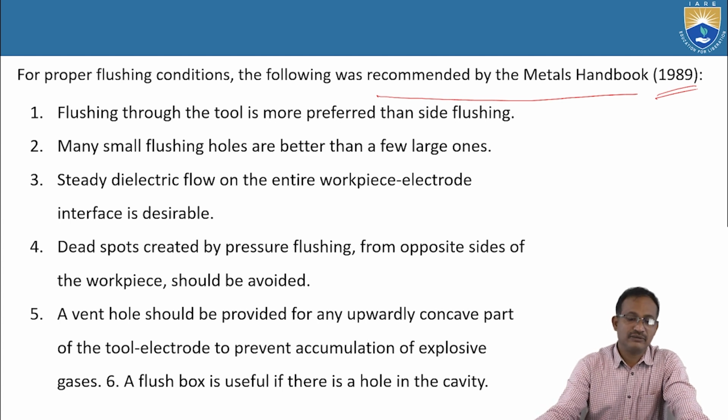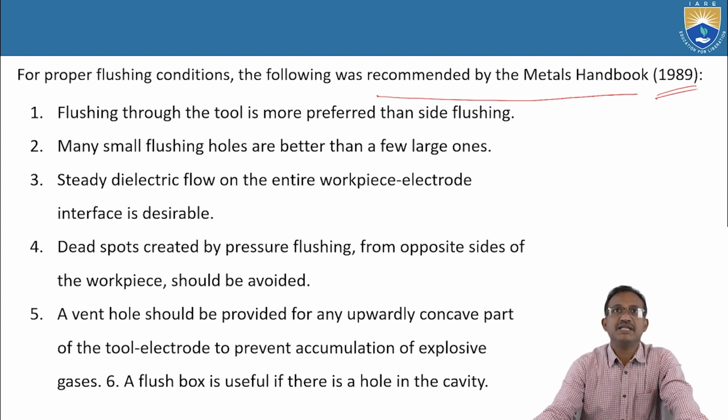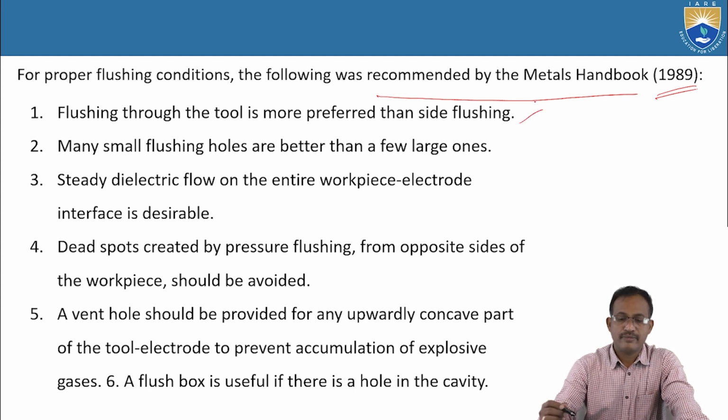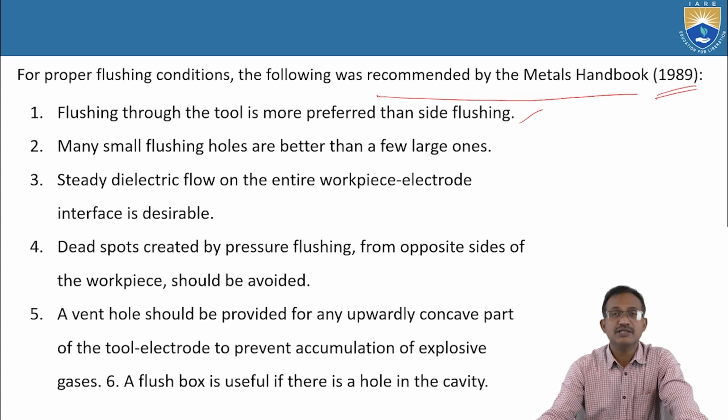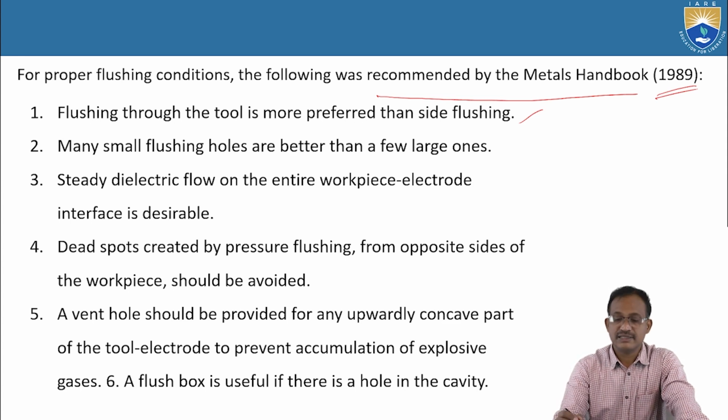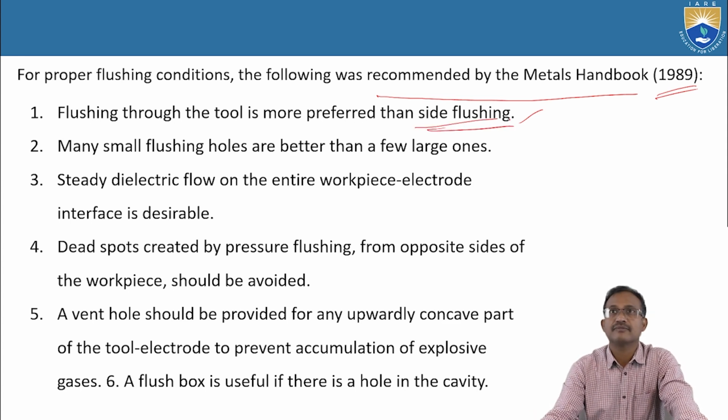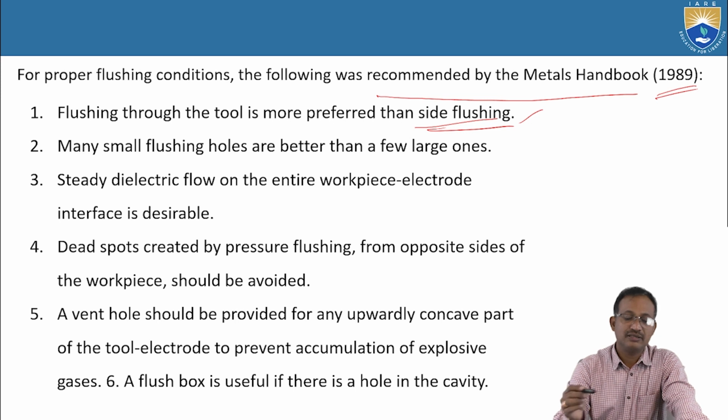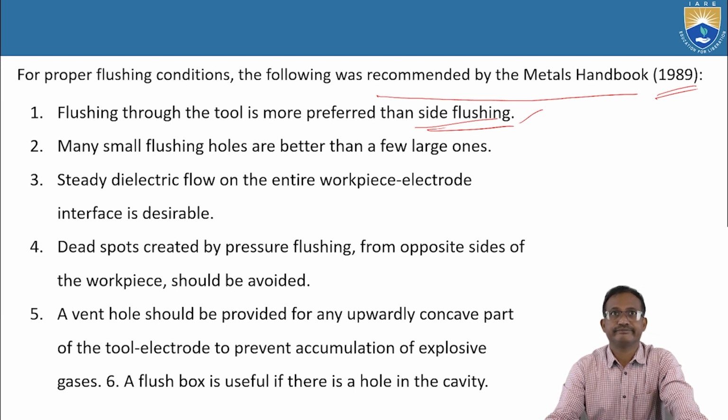Okay, first one, flushing through the tool is more preferred than slide flushing. So instead of slide flushing, we better prefer flushing through the tool.